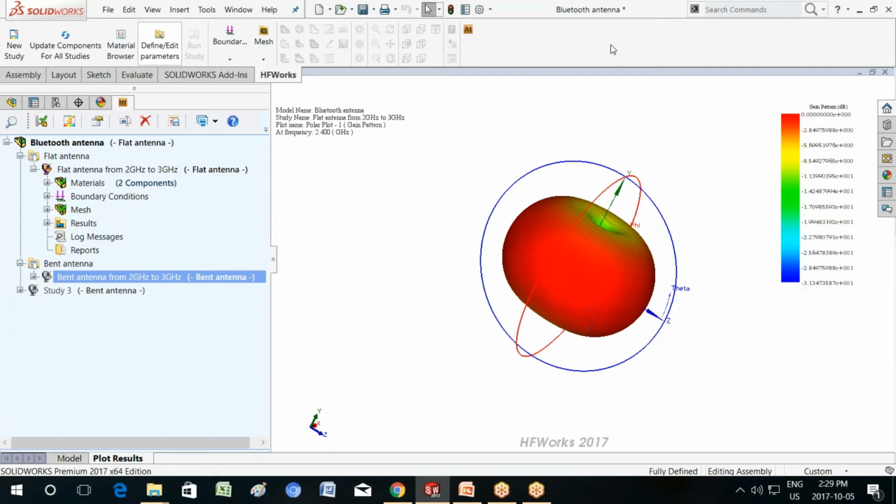Okay, so for all intents and purposes, if I'm looking at 2.45 gigahertz, I can see that my antenna is still functioning. So without much additional design tweaking, if I place this antenna at 2.45 gigahertz, I'm going to get about 13 dB, or better than 10 dB return loss. So it's not bad. The bending issue, as far as the matching goes, is not a big issue.